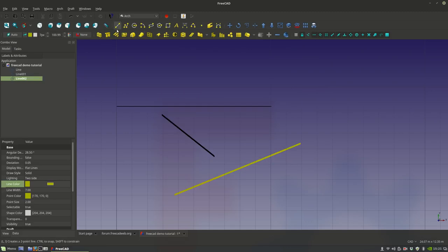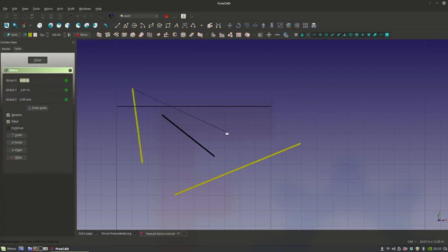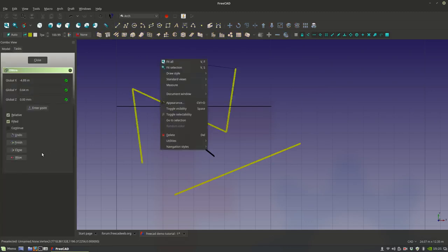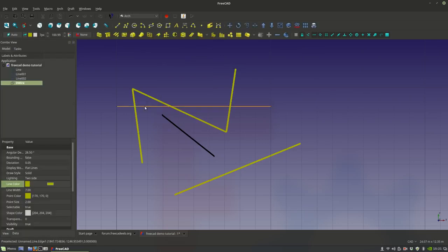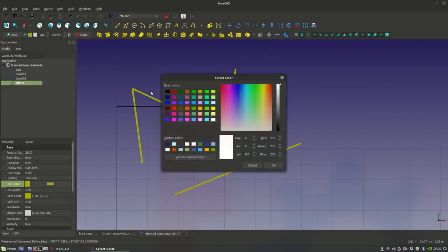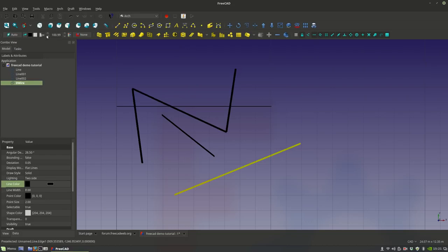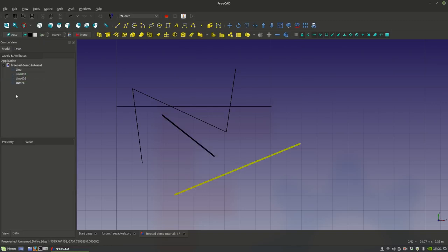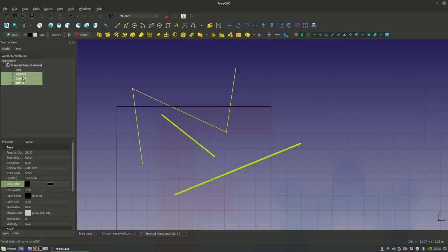So this is where I can predefine the initial settings of the type of line, right? So I'm gonna set this back to default and probably set the line thickness back to 2. Okay, just like that, and then I'm gonna delete all these new extra lines.